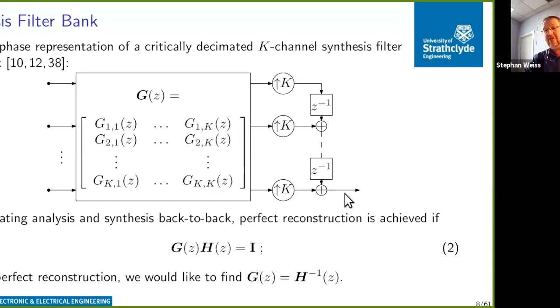And if you now imagine these two constructs of the last two slides working back to back, so you have your demultiplexer, your polyphase analysis matrix, the polyphase synthesis matrix, and the multiplexer, then if the inner part multiplies out to an identity, the multiplexing and demultiplexing operation is transparent as well.